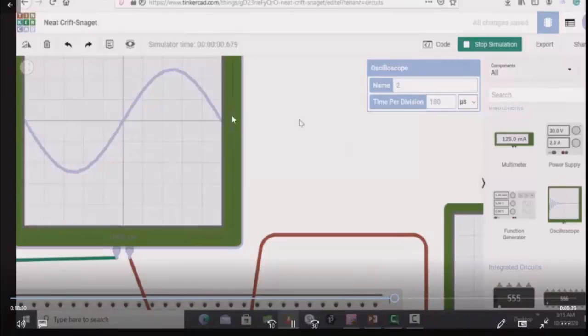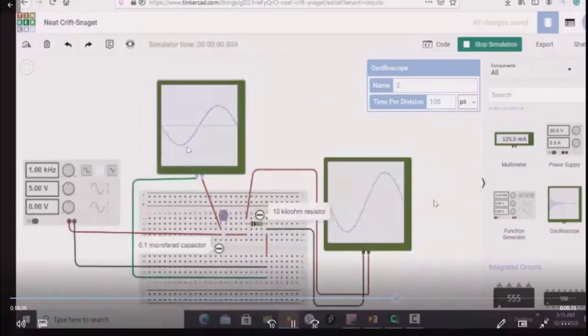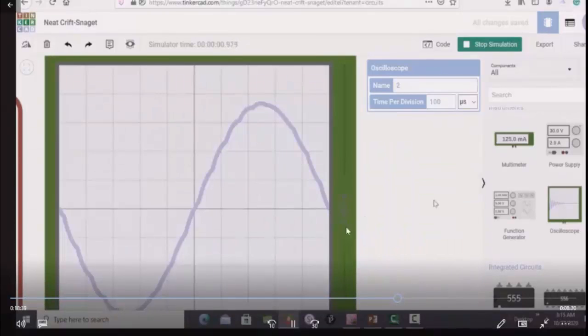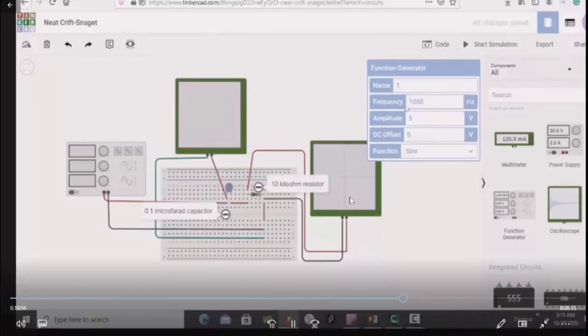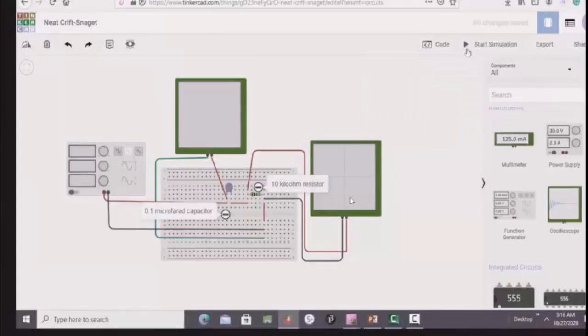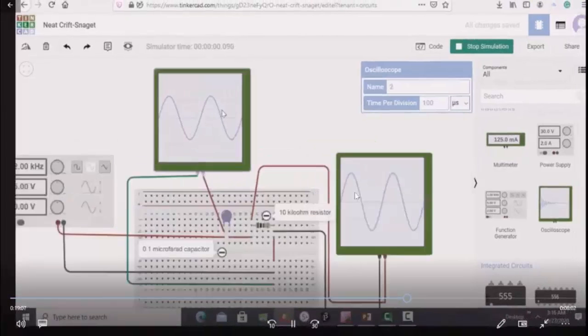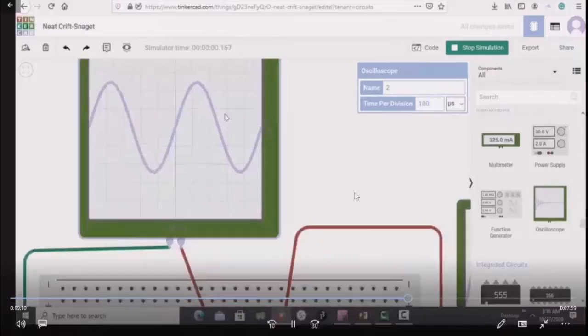And I can see, you see here in blue you have 10 volts written down, right? And this is 2.5, 2.55, and this is 2 volts. So on the 2 volts thing, you can see that this is 1, 2, 3. So 10 divisions correspond to 2 volts. So each division or each square of this is equal to 0.2, and this is close to 8 squares. All right. So this is very less voltage. Okay. So when the frequency is less, the voltage is less. As I go on increasing the frequency, the output voltage is going to go on increasing.